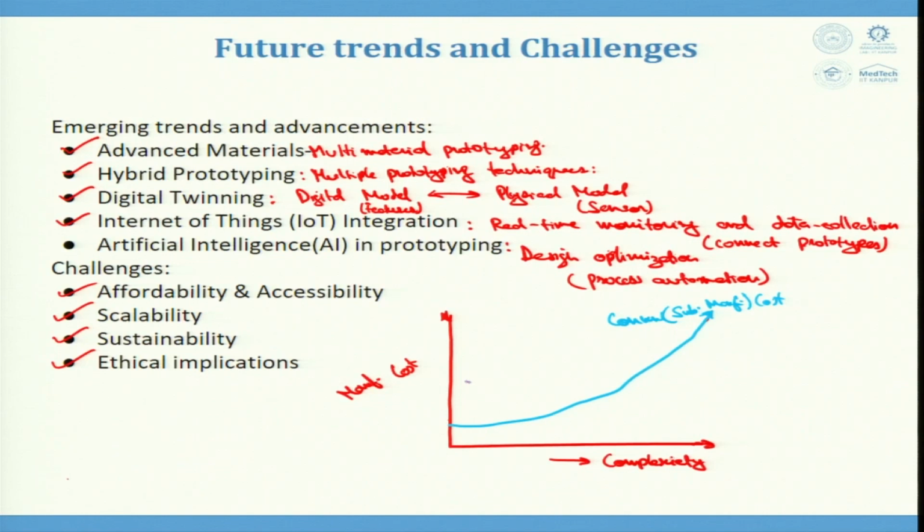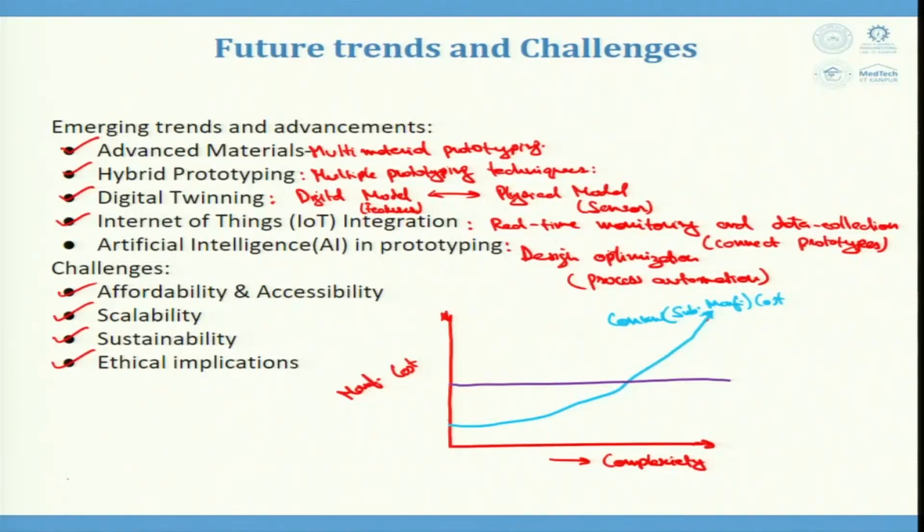However, additive manufacturing cost is almost the same for any of the complex products, because it is only the CAD design that is taking time. Rapid prototyping or additive manufacturing has to happen layer by layer. The cost of the products remains the same for a single piece or for 1000 pieces. In conventional or subtractive manufacturing, even if one piece is to be manufactured, we still need tooling for that.